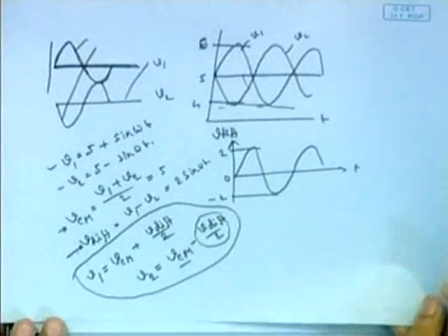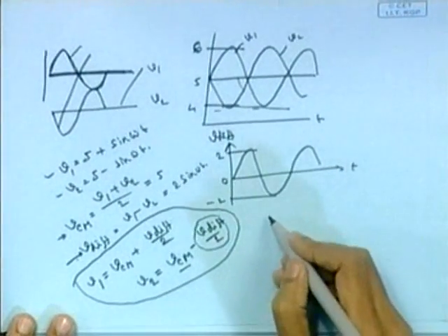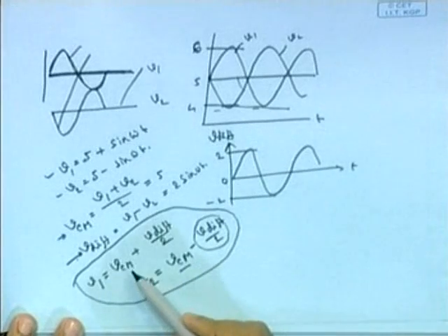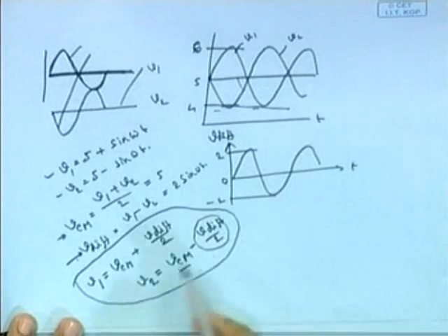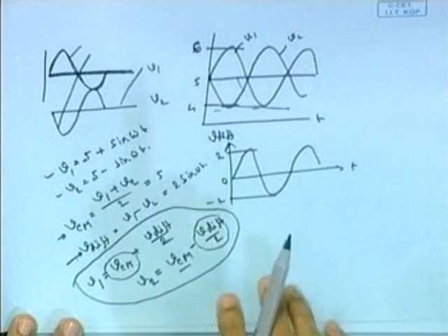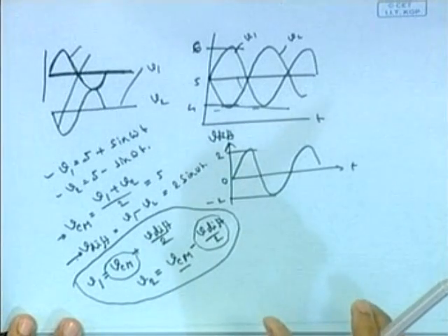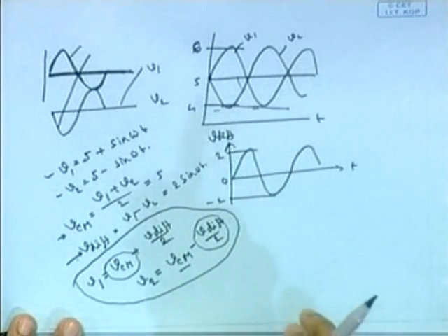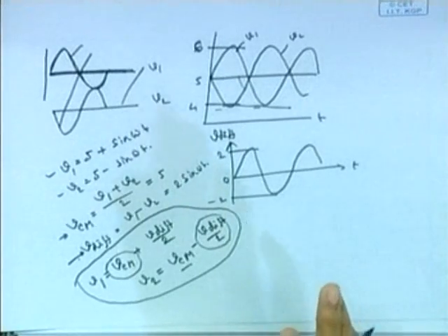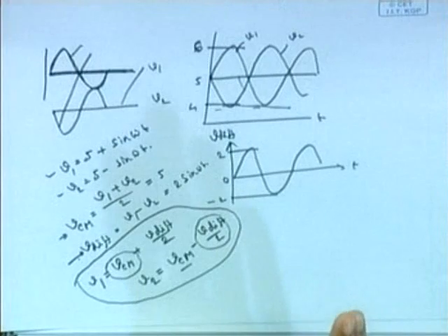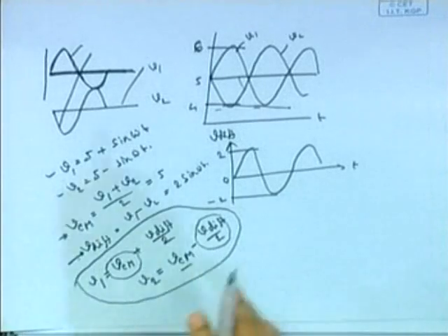So this is the thing, and the third is the input common mode range. They call it ICMR. For a particular differential amplifier, you cannot apply any VCM to the circuit. There is a limit, and that limit is dictated by the condition, as I told in the earlier class, that we always want all our transistors to work in the saturation zone. So that condition dictates what VCM limit we can apply to the circuit.